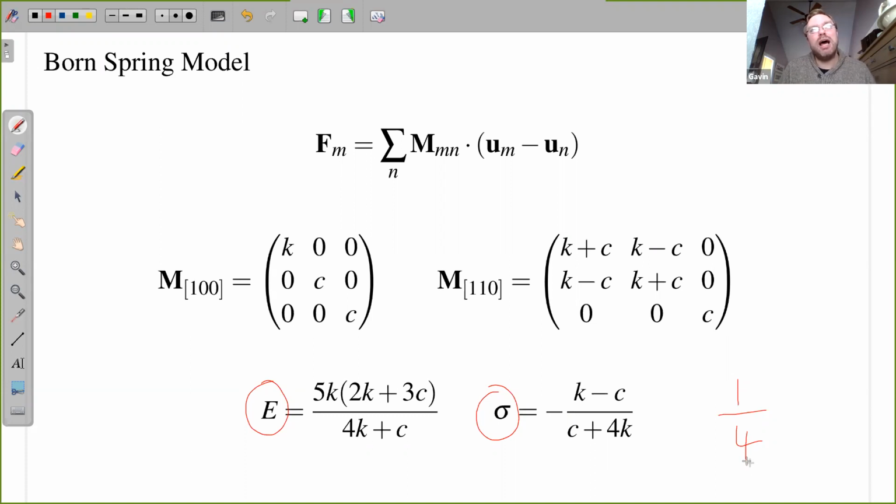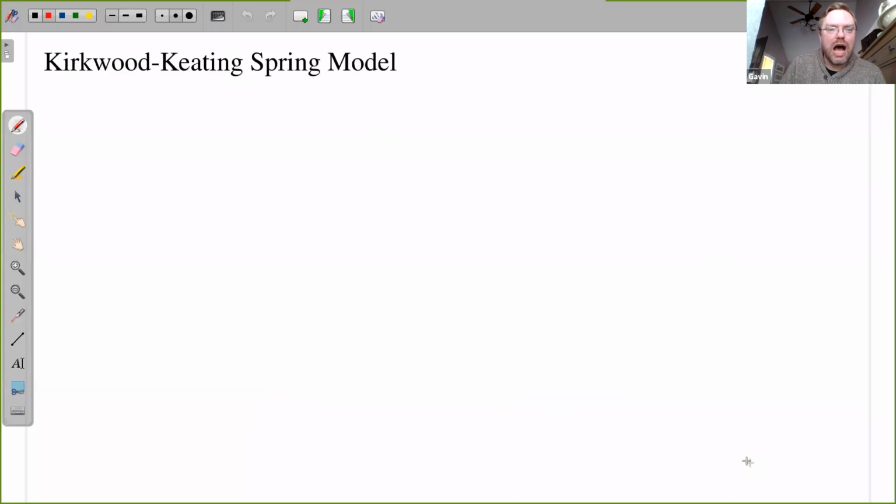There have even been people who have mapped the spring model onto a displacement-based finite element method, and that way you're just solving the finite element method at that point. So there are more complicated ways of writing these and getting more variations in those elastic constants.